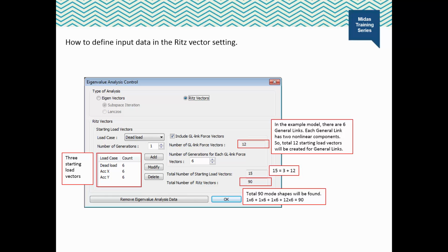In the above example, we have used 270 eigenvectors for analysis. The reason we have used 270 modes is that 270 is the maximum number of modes. So in order to have accurate results, we should include all the available modes, and hence we chose to input 270 modes. But for Ritz vector, we can see that there were only 90 vectors required to obtain accurate results. Undoubtedly, as I mentioned, using a small number of vectors will require less time for analysis.